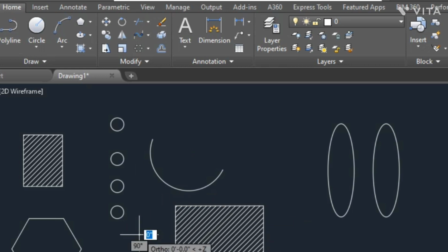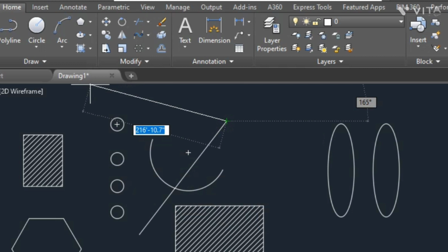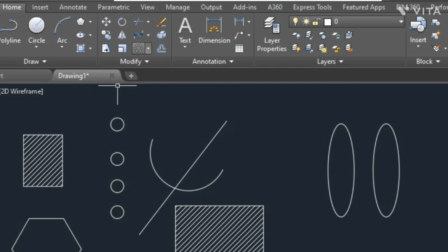Next is the trim or extend option. There are two options there. You can trim it or you can extend it. For example, if there is a line you want to trim, then select the option trim and then select the line, click on the object from where it is to be trimmed, then select the line that has to be trimmed. Your line will be trimmed.